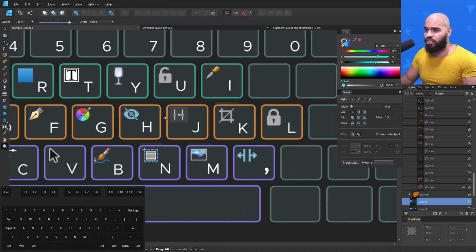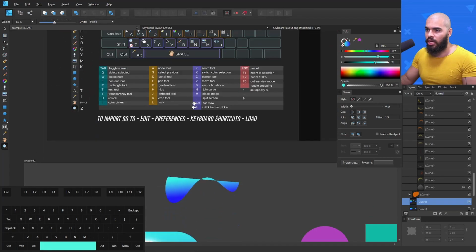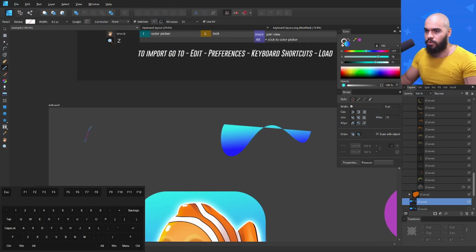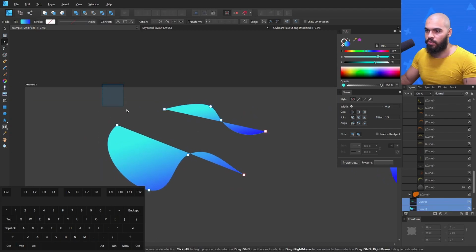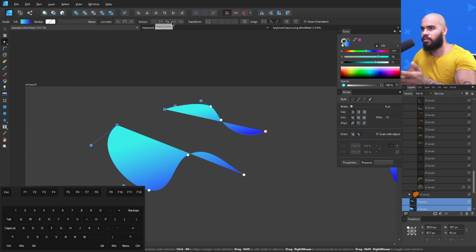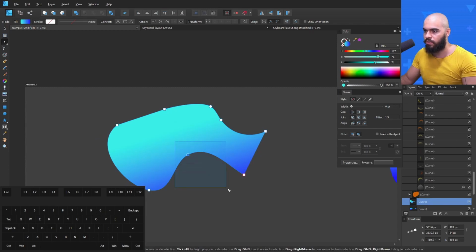Here on the J is gonna do what? Let's put that you are drawing like this and this shape. The J is gonna do the join. Let's say that you want to select these two nodes, and instead of going here and clicking join curves, you're gonna press J of join curves. Click here, select two nodes and join curves. There you go. Join curves.